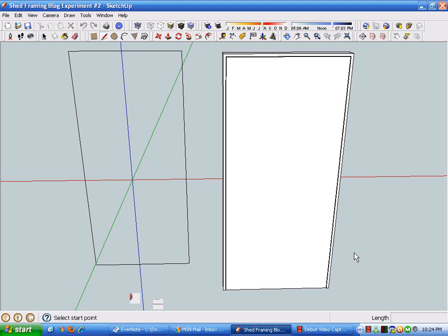Finish up this post and finish developing the outline of the different pieces of this door component. We'll develop the brick mold component of it and again use the follow me tool to create an architecturally accurate brick mold.